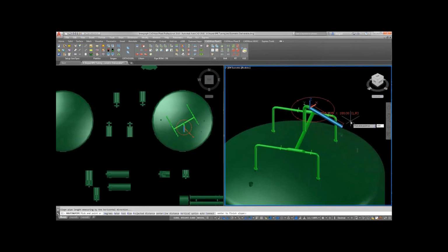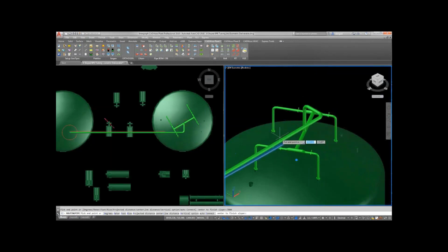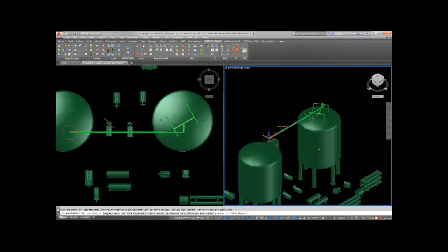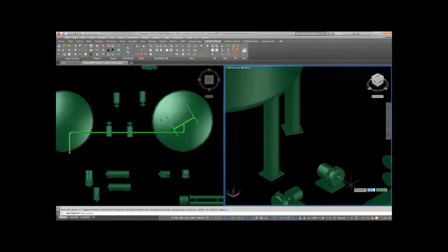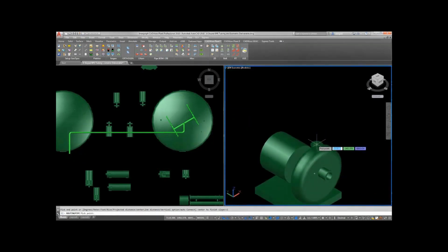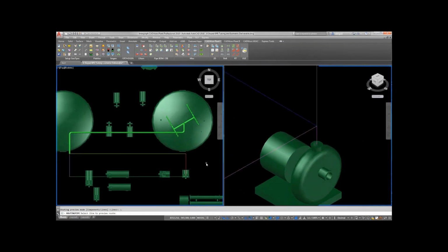I have selected the meter option in this, going for defining a length, and following that, I want to make a connection from this end to where I am stopping, and then going for auto connect to connect that to the pump end. Now, once I define this, as usual with the auto route options, we can choose which line options you want to proceed with.